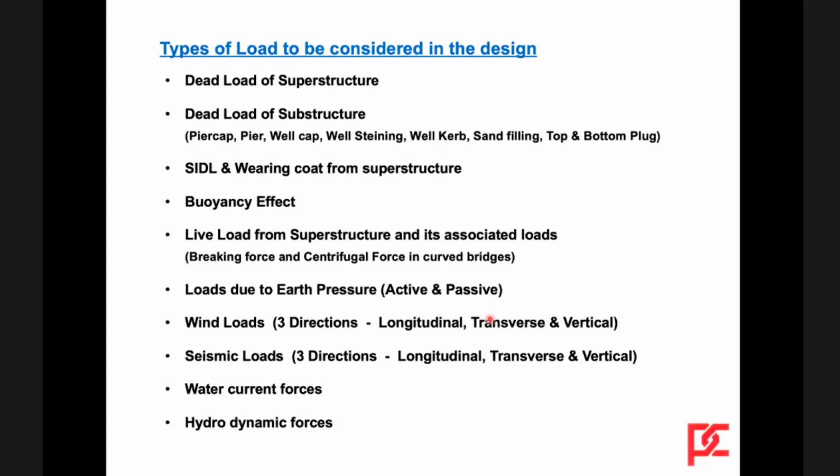Then the types of loads to be considered in the well design: loads from superstructure, substructure, pier cap, pier, well steining, well cap, sand filling, top and bottom plug, SIDL, buoyancy effect, live load from superstructure and its associated loads, loads due to earth pressure, active and passive, wind loads, and seismic loads in three directions: longitudinal, transverse, vertical, water current forces, and hydrodynamic forces due to seismic.